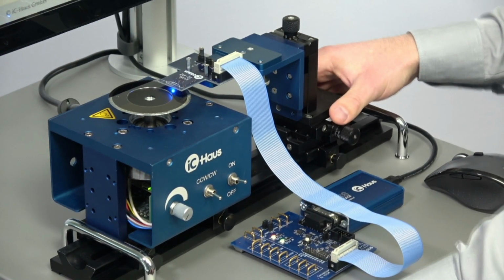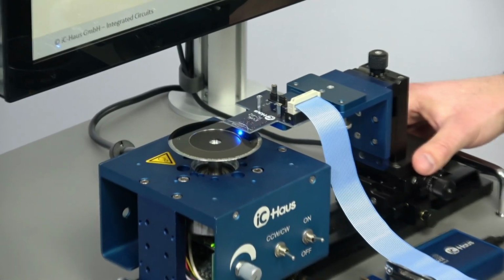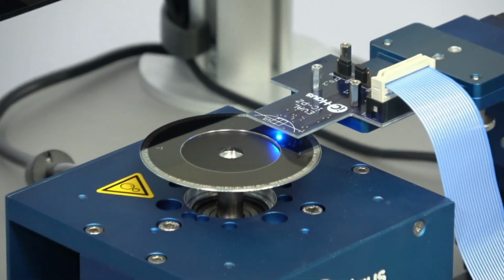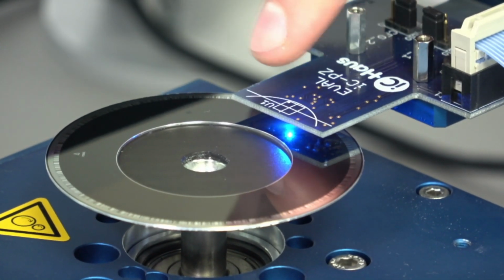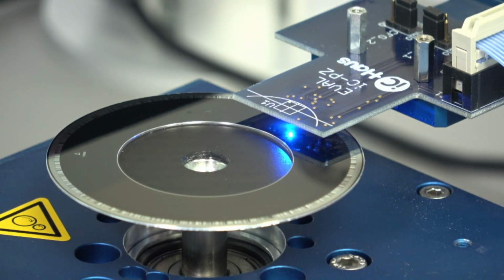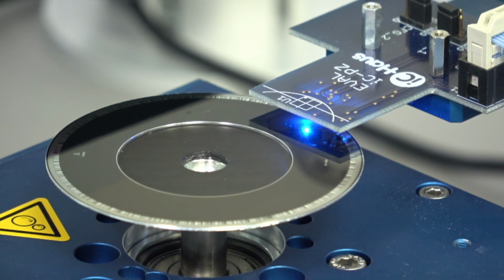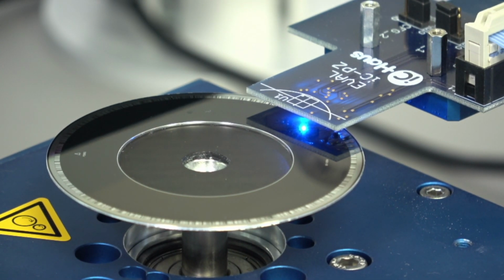And what I'd like to show you now is that there are two indicators that can be used very nicely to align the system. First one, when using the PZ1M, we do have the white alignment marks printed on top of the PCBA. So there's kind of a cross that really wants to be in the middle of the two code tracks. And the second one is the blue LED. As you know, we do have an integrated LED power control, and what it does is, when there is no signal coming in from the code tracks, this will shine very, very bright blue.